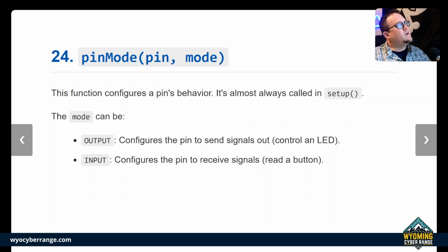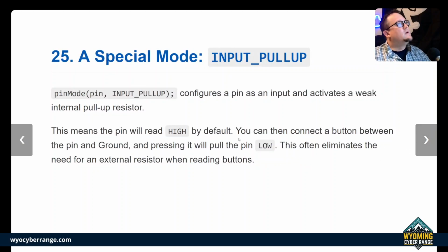So remember when we were talking about pin mode, we have outputs and inputs. So it all depends on what we're connecting up to it. An LED is an output, but a button is an input. Now, depending on the different types of inputs, there is a pull-up method. And you're going to see this in today's lab, okay?